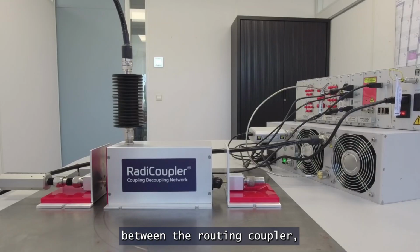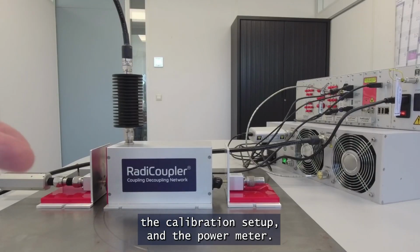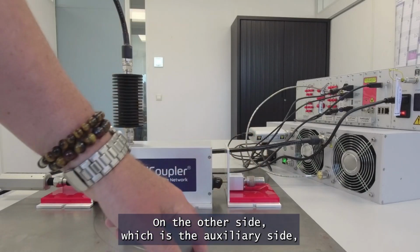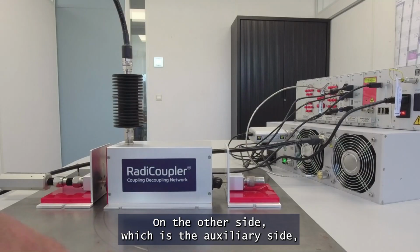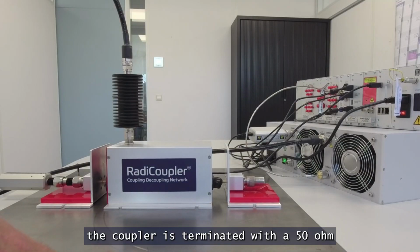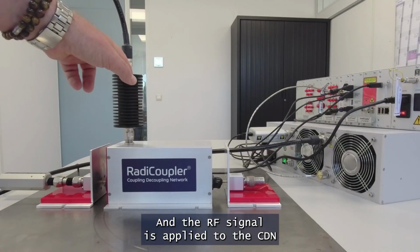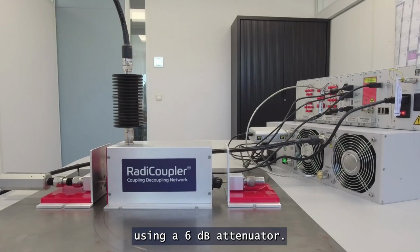Between the Radicoupler, the calibration setup, and the power meter, there is an additional attenuator. On the other side, which is the auxiliary side, the coupler is terminated with a 50 ohm termination. And the RF signal is applied to the CDN using a 6 decibel attenuator.